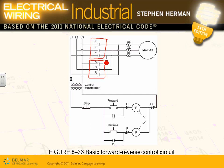Here's the mechanism. When you push the forward right here to go forward, it will open the reverse. At the same time, it closes this one, and the motor is going forward, right? And at the same time, it opens this contact, guys, to prevent you from closing the reverse button and having a line-to-line short. When we reverse a three-phase motor, Karen, we always switch two phases, phase 1 and 3. Flip them. That's what reversing a three-phase motor is.